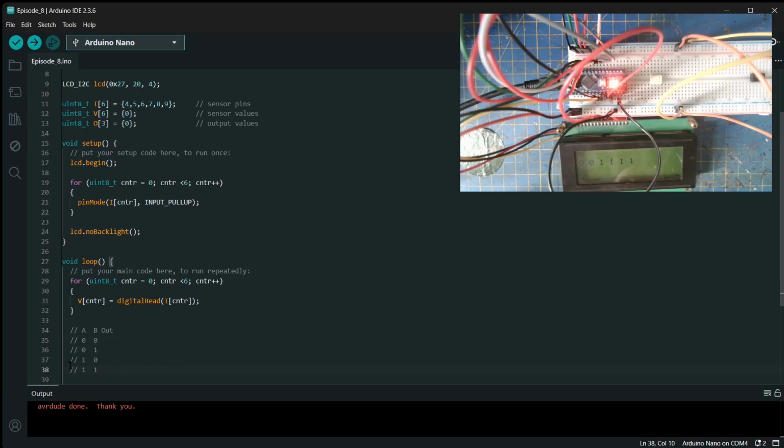So where neither of them are reading there's a train, what I want is a 0, because this is going to drive a relay. When there's no train, I don't want the relay driven. And if both sensors see a train, I do want the relay driven. In fact, if either sensor shows that, that's what I want.